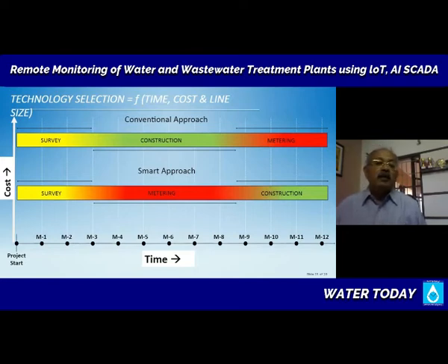Now, in modern times, whereas in old cases your metering may come up in month number 10, after you have started thinking about metering, now with the clamp-on technology, once you know where to put the meters, as early as the second or third month of the project, your metering installations can begin. It means that all the 6 or 8 months of metered data will be available for you to manage your water network. And 6 or 8 months of measured data may actually justify your project budget almost entirely,